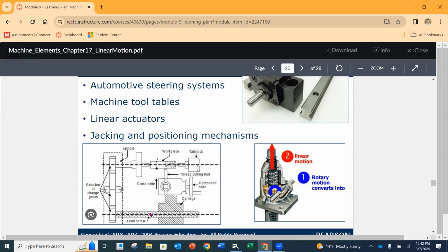Drive on them. So a lot of the things you cover, they're higher accuracy, higher cost, but less friction, so less heat. Get more speed out of them too. Some of these machines are moving heavy loads back and forth, up to like 15 meters a minute or something. So they can go pretty fast. As the technology's got better on screws, the ball screws, you'll see machine tools can start moving at a faster rate, so they can cut metal at a faster rate.